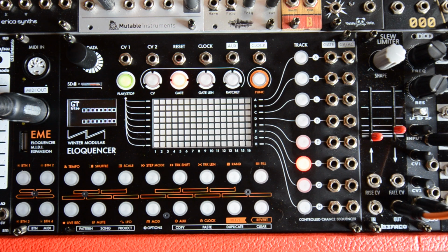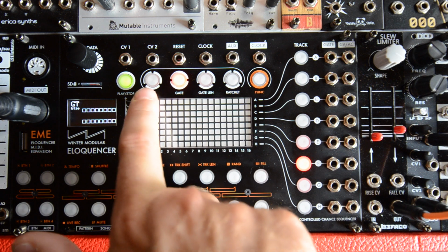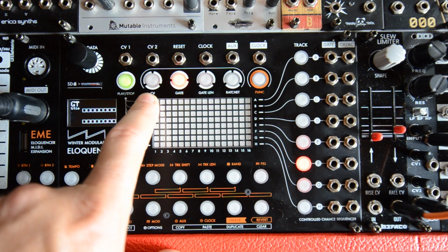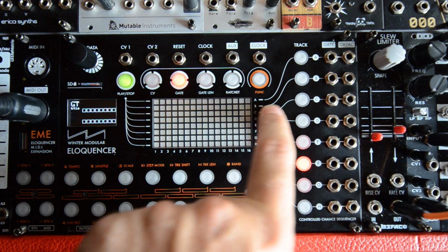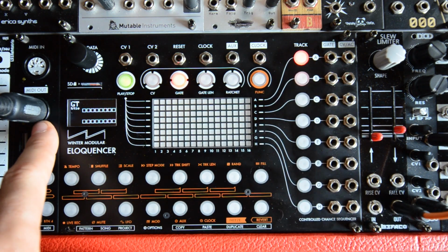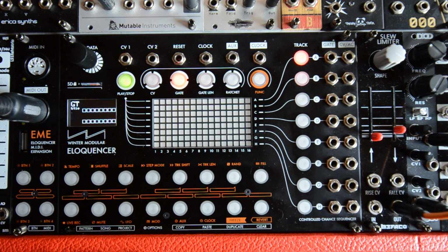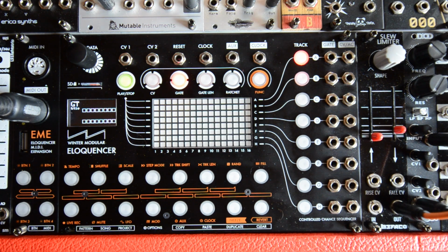We can continue with the MIDI out. The thing is, our CV and gate values that we have in our sequence, in our track, can be converted into a MIDI message. We have three different types of MIDI message: a voice message that includes note on, note off, pitch and velocity, control change message, and program change message.